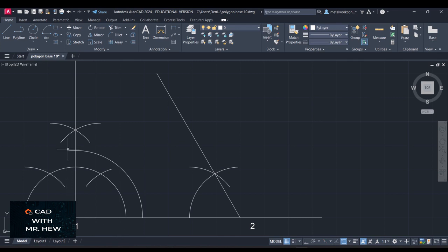So what we did, we constructed this line, which is a 90-degree. Good. Then compass at 1, any radius, we mark an arc which is greater than this semicircle to intersect the baseline and the 90-degree line. So this is the line that we're working with. Good? Good job. So again, we're constructing a 45-degree angle at 1. The first procedure was to draw this arc, then mark an arc to intersect the previous arc from where you see that red highlighted dot to give you this arc.